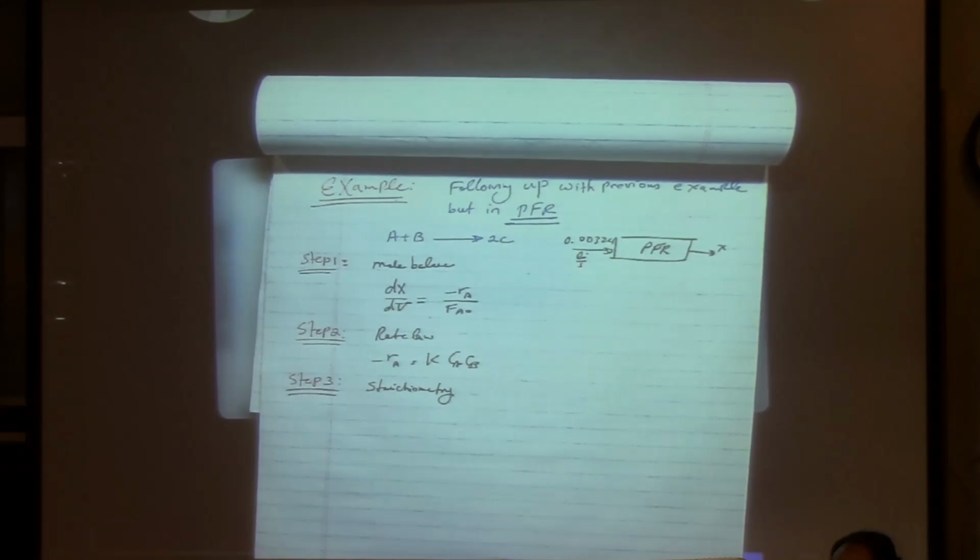Obviously, if there is liquid, you already have a simplified version, so you have a relationship between the concentration and conversion. If there are gases where the moles don't change between left and right, your delta and epsilon are 0, so again you are in the easiest case.